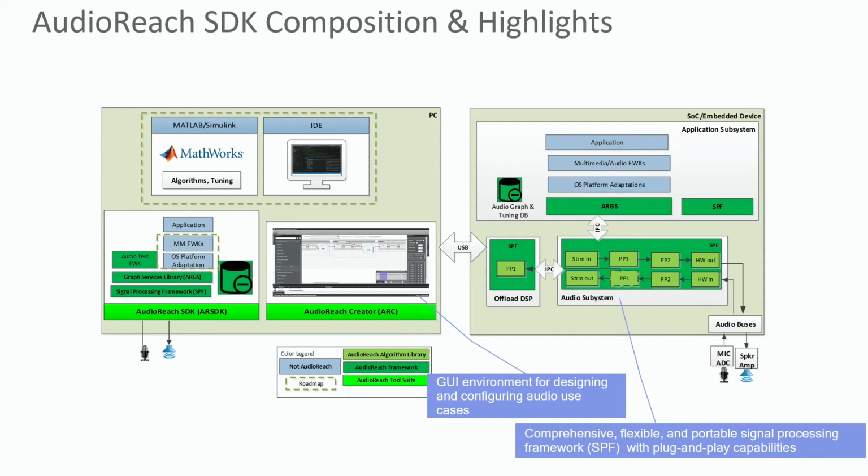It's highly flexible in allowing plug and play. You can easily drop in algorithm modules. It supports dynamic loading, so you don't have to build all your use case modules into the DSP image by itself. It's highly portable. It has a clean separation of a generic framework as well as a layer we call the platform OS abstraction layer.